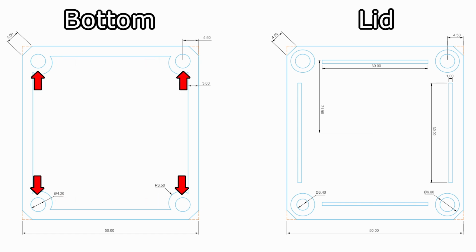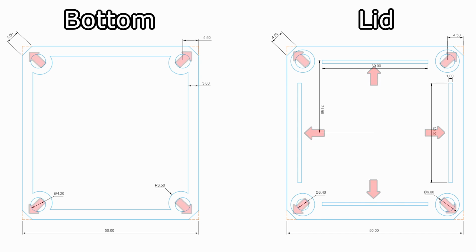The box will be hollow, except for 4 built-in standoffs, allowing the lid to be screwed on, and holes will be added to the standoffs so M3 threaded inserts can be installed once the model is printed. The lid will have thin alignment guides to help when securing the lid and bottom portion together, and both parts will have chamfered edges. Since the box will be designed for flathead screws, the screw holes in the lid will be countersunk. Now, it's time to fire up the slicer.